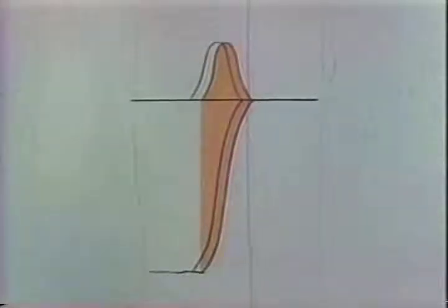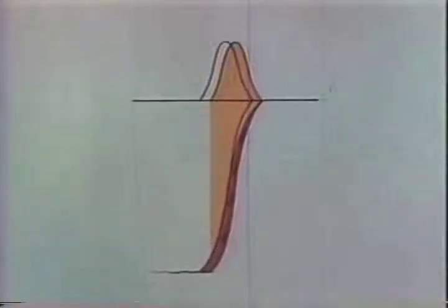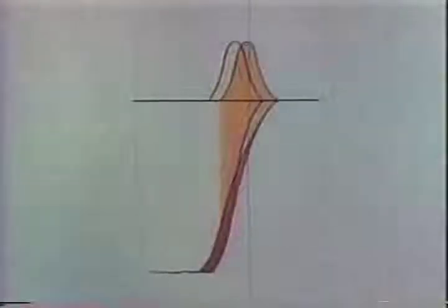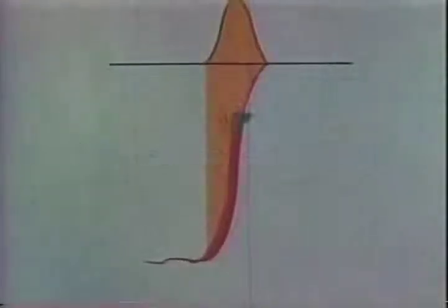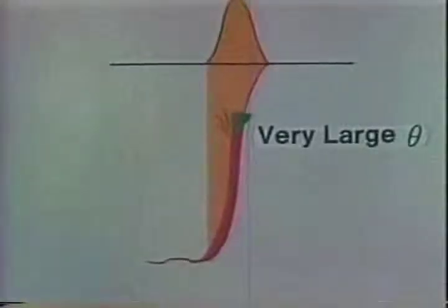On the other hand, if there is melt flow at the front wall, what will happen there? The lower part of the front wall is buried by the successive melt flow, and then the forward advance is prevented at the bottom. As a result, the angle becomes too large to balance with the heat input intensity, and thus there follows a local breakdown there, producing a shoulder-like front wall. The localized breakdown occurs so as to increase the inclination angle and hence accelerates the scrape-off rate at the wall.